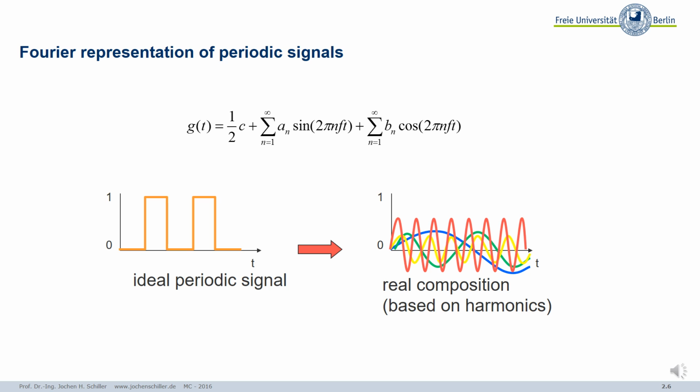And here, if we transmit over the air, that means over space, without using our antennas, we'll see we have even more restrictions. I already told you the antenna size pretty much depends on the wavelength. So if I create a mobile phone that should fit into a pocket, I should use electromagnetic waves with frequencies that fit small antennas, because I'm not a submarine, so I cannot have a long antenna. That's what I told you the last time about Marconi. They created these 100 meter high antennas, and then they could transmit something.